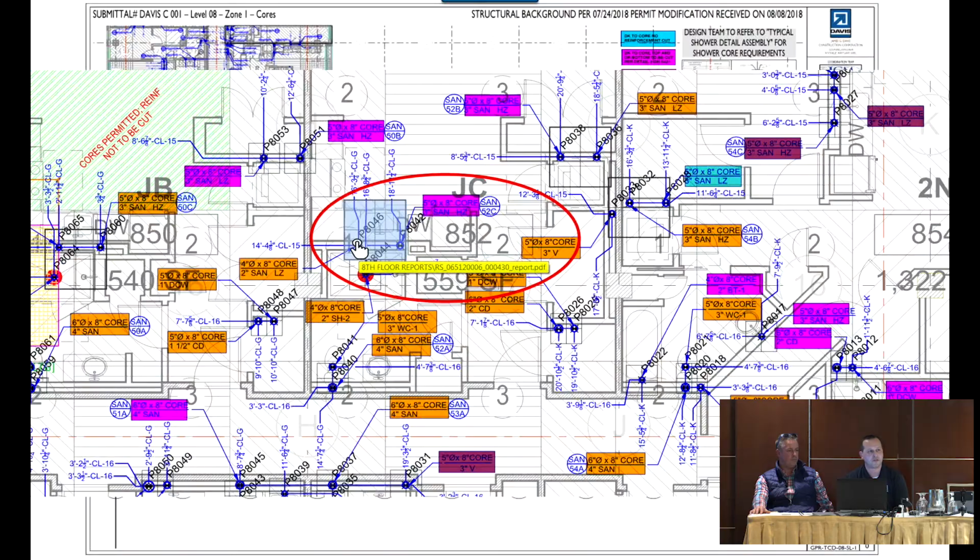When the structural engineer gets these documents, we provide a complete package, inclusive of all electronic files, because another challenge we had in the past was when a core is individually relocated in the field, if you're looking at those GPR marks on the slab, it's very hard sometimes for the designer to determine, should I shift that whole wall 40 feet down the line, or should I just deal with this one core? Providing everything electronically to the design team allows them to study if a core needs to be relocated. Here's your plan overall. If you need to relocate a whole wall, it's a lot easier to share and discuss that information.